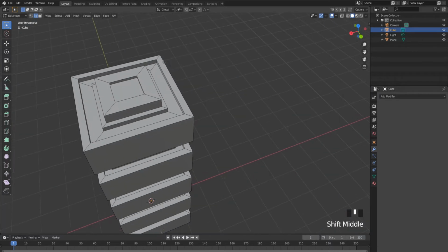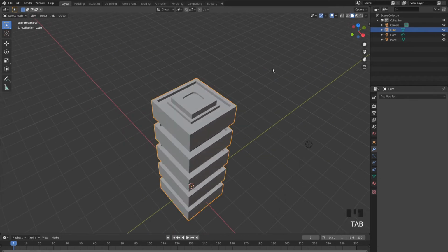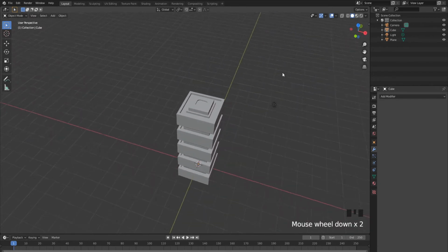Make sure you're holding Shift throughout, and then when you're satisfied, press Ctrl B, and that's going to bevel the edges. You can scroll your mouse wheel up and down to change the amount of extra vertices you're putting in here, so that you can make it smoother or more blocky if you wanted to, but I'm just going to put, say, about 5 in. Make it only a subtle curve, and that looks pretty good to me. Okay, I'm going to stick with that for now.